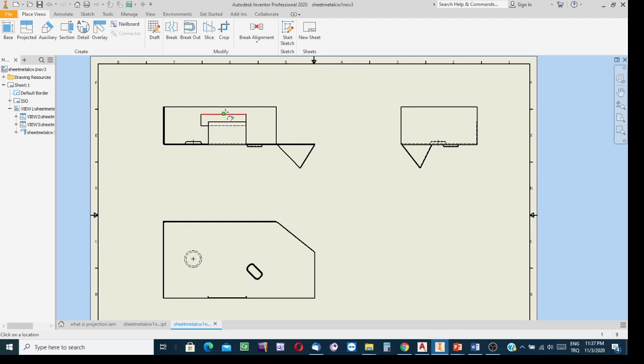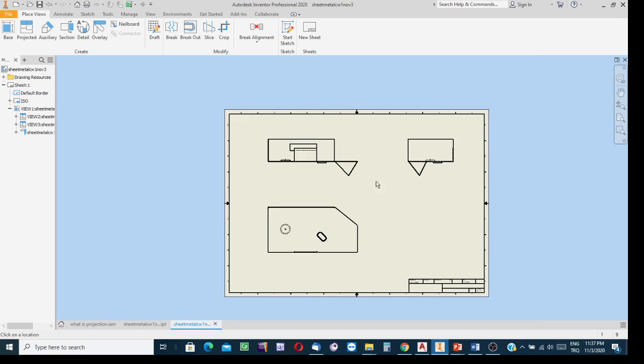If you had an interruption at the view creation stage, then to be able to create one more view, for instance, well, I created these views, after that I stopped. So I had an interruption. But thereafter I decided to create not only those but one more view. Then I need to click on the projection button. Click on this one, indicate the front view as the reference, and then for the right side view, go in this direction and create the right side view as necessary. Okay, such things. Well, the advantage of starting from the front side view, etc.